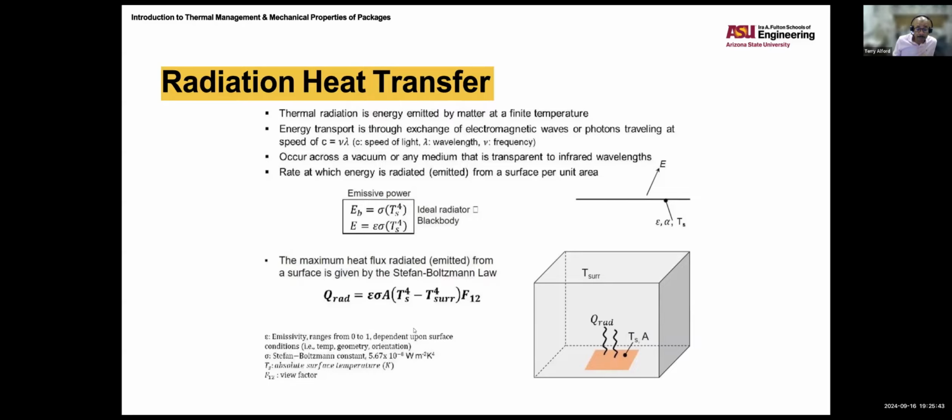But I'm still getting heat transfer through the package. But with this type of design, utilizing the TIM and the heat spreader, I will get the majority of the heat moving out through the TIM and the heat spreader. Now, again, what's the advantage? Yes, I get the heat off much better, but it's more expensive because it's a more complex configuration.